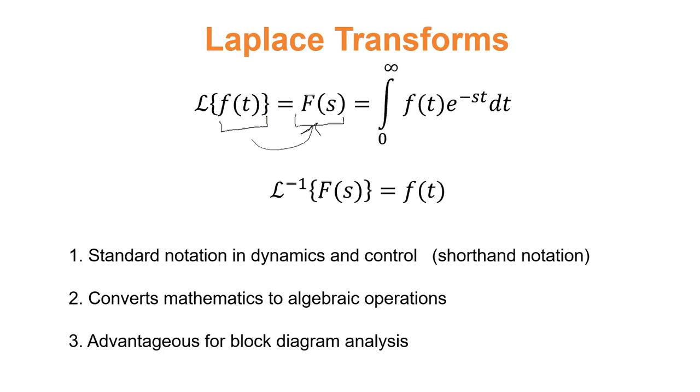We've talked a little bit about block diagram analysis, but as we get into more sophisticated analysis of process control systems, we'll draw loops as blocks where we can use these transfer functions, something we find in the Laplace transform domain, to represent the individual components of a process control system within the loop.